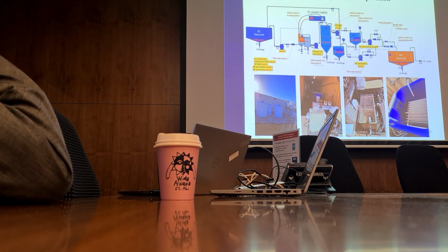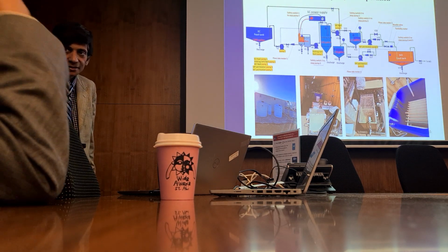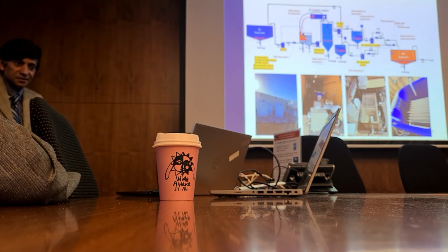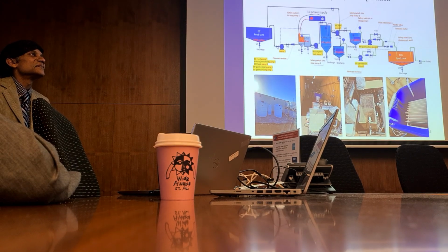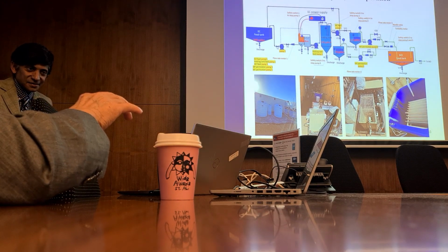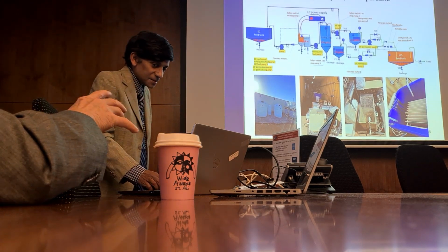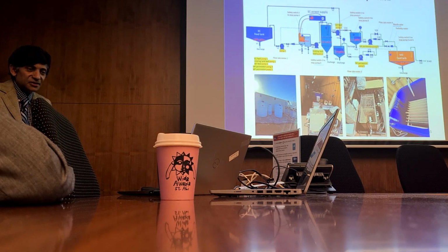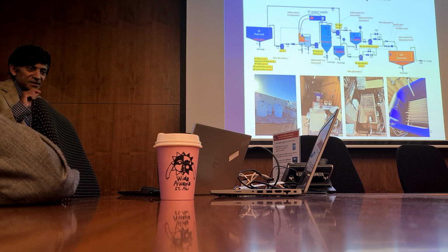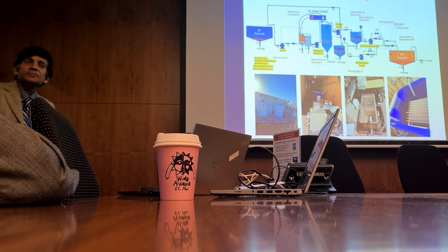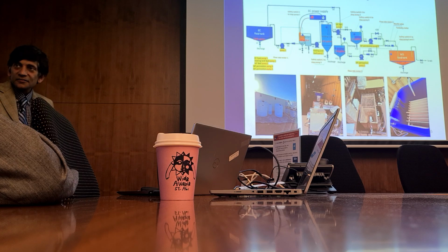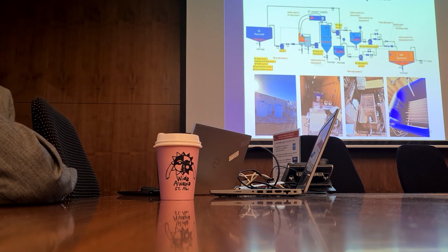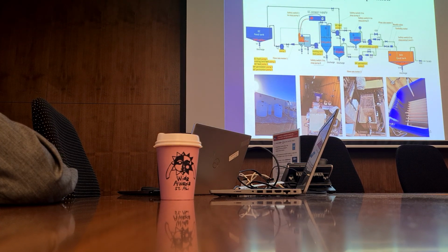Okay, let me continue the question that Professor Sean asked. On MD, what was the TDS, total dissolved salt, going into the MD, and then after MD, the discharge from MD? This bit I have to look up. I have forgotten what our limits were for TDS going into MD. It's in the publication, and you can check that. But we had set these limits based on experimental results and the stability of the MD membrane. The discharge is something Marty did, and I am not exactly sure what levels he got to at the very end of it, but I will tell you later. I can check the paper.